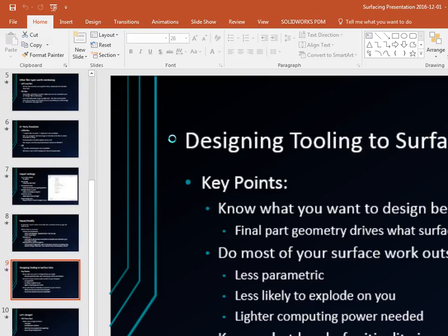Honestly, I don't fillet surfaces much because I've had better luck waiting until it's in the solid and then filleting it. But it does mean that my final part has extra work in it. It has those fillets in it that SolidWorks might think it needs to rebuild. Usually when I run into it, it's something that's maybe a sweep or a radius, some weird thing, and there was a cutout in it, and now I'm trying to fill in wherever that cutout was, and you're trying to patch all that weird geometry.